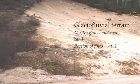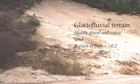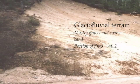In every watershed in BC, we look for deposits of gravel for our road bases. They have very few fines in them, and they are used for lots of road capping material. Roads built on such landscapes are generally very forgiving. There's not a lot of sediment to generate, and any water generated is quickly infiltrated back into the soil. A road contractor used to building road on these coarser sediments can come into serious disadvantage when dealing with less forgiving landscapes.